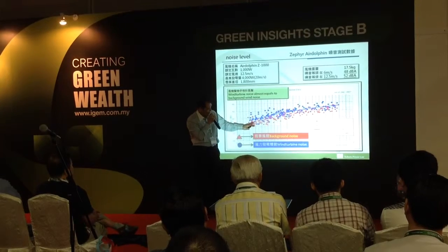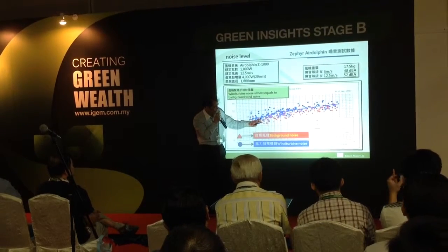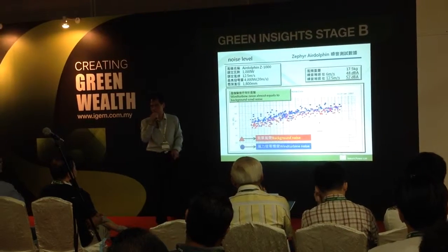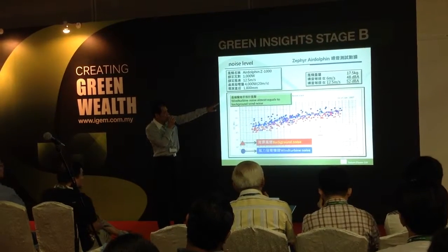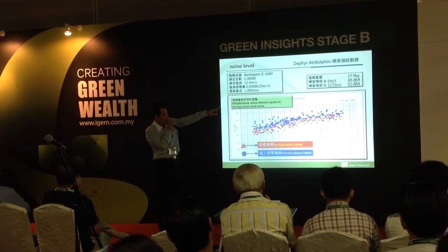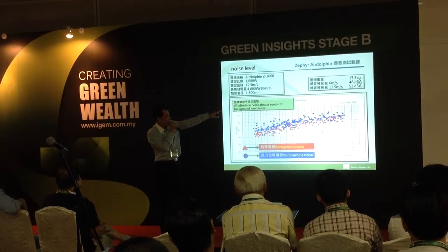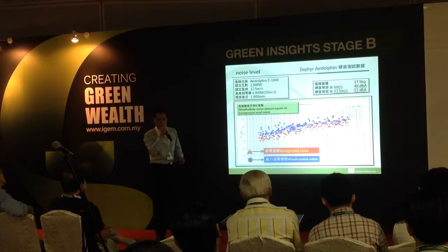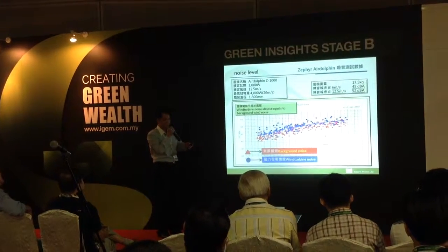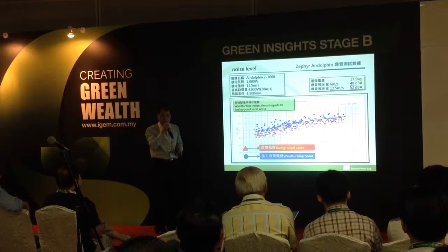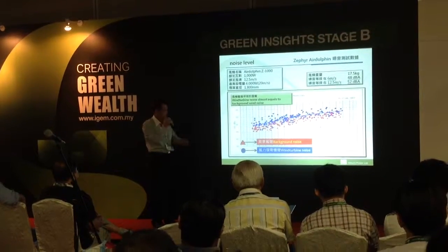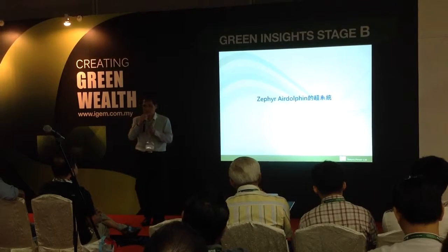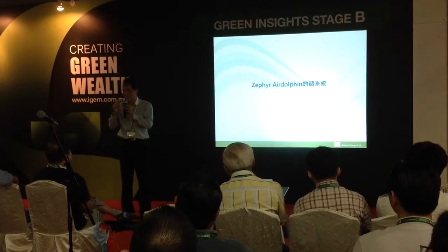At different speeds, we also cope with the background wind noise. So we have 6 meters per second at 48 dB, and at 12.5 meters per second, we have only 52 dB. So this means our imitation is quite successful. I think my time is running out, so